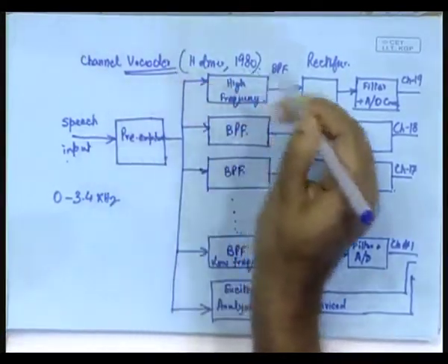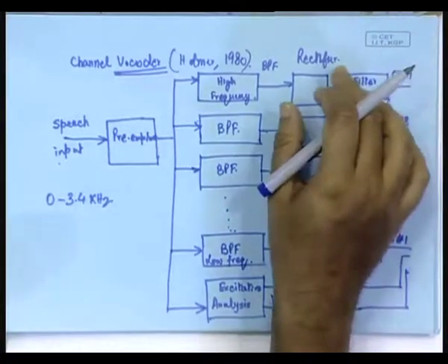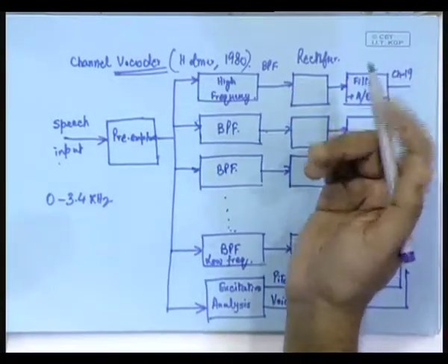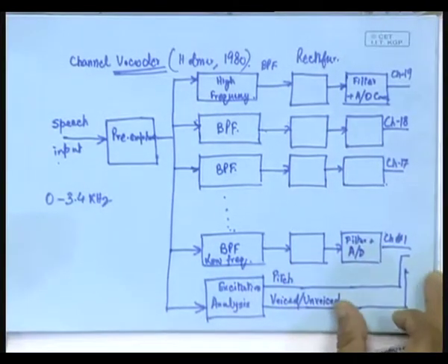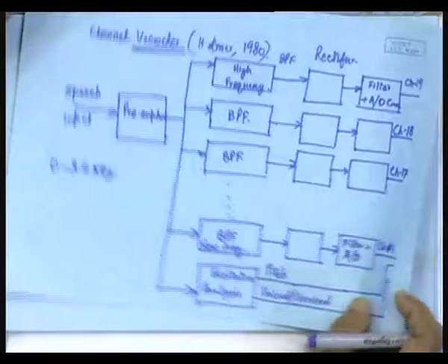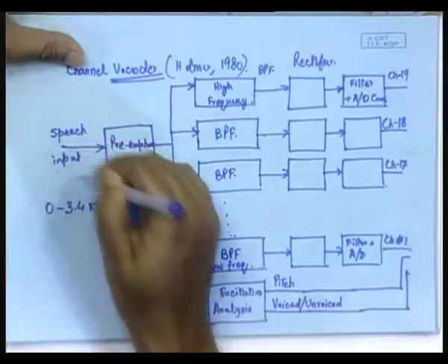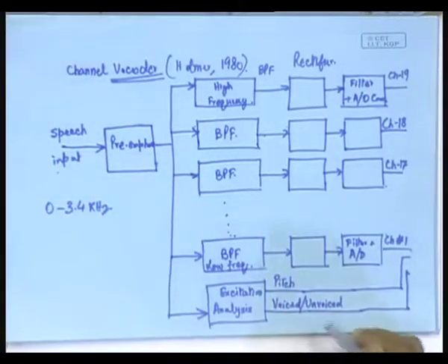The word vocoder basically originates from voice encoder. Okay. So, it is a very popular thing, and this methodology is essentially what we have done here, a kind of parametric coding. And why parametric coding? Because we are not approximating the speech waveform like we do in the case of say pulse code modulation or the adaptive pulse code modulation and so on, which is essentially a waveform approximating technique.